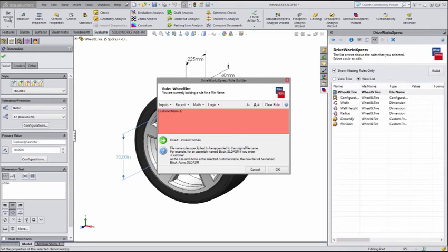If you want to do specific text callouts in logic, we have to use an ampersand, so it's going to say your name and then, in parentheses, this specific character. We're going to go with an underscore, and then parentheses again. And you can see there in the result, it says your name underscore. I'm going to do this a couple times, so I'm going to start another ampersand. I'm going to copy that little string to my clipboard so I can paste it easily.